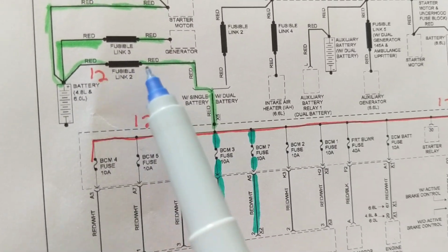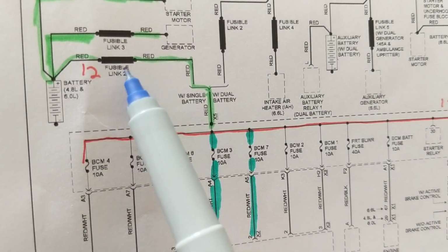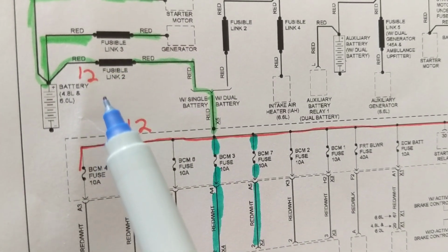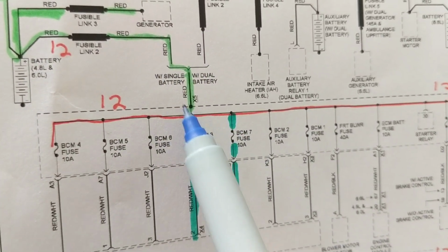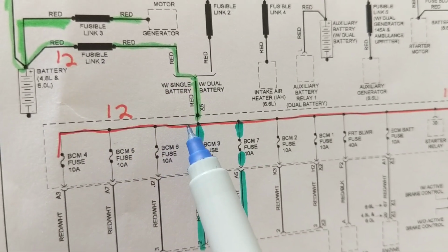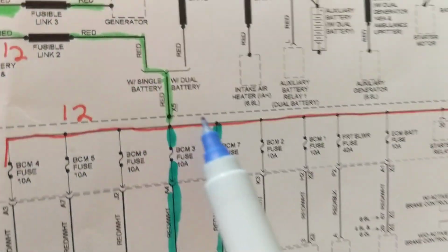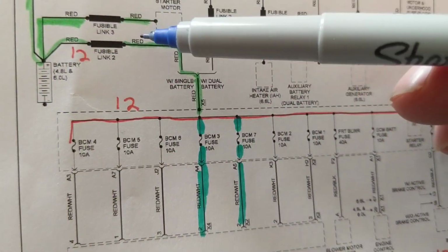12 volts should be here. Why? We said current is flowing, but there's no voltage drop across here. We do not lose much. There is very low resistance. So 12 volts here, 12 volts here. Why 12 volts here from here to here? It's a wire. We're not going to lose much voltage drop. By voltage drop, I mean from this point to this point.